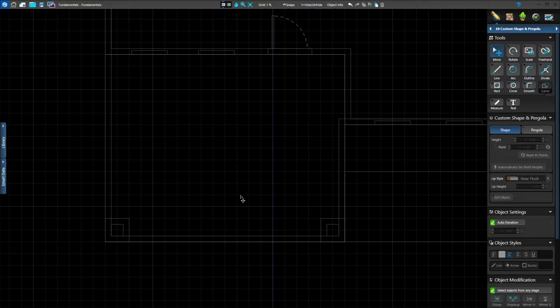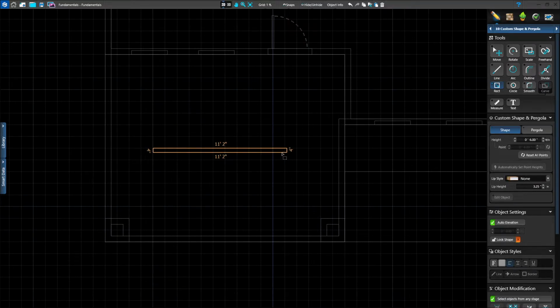The first shape I'm going to draw is going to be the base. I'm just drawing the shape and setting the height, and that's all I have to do. But I'll use some aligning tools that are really helpful, and we haven't done any aligning, so I want to make sure that you see how to do this. Anywhere in this open grid space on this patio, we're going to make a 10-foot by 2-foot rectangle. Just activate your rectangle tool, go anywhere in this space and left click, and come to the right 10 feet and down 2 feet. When you get that all squared away, left click.